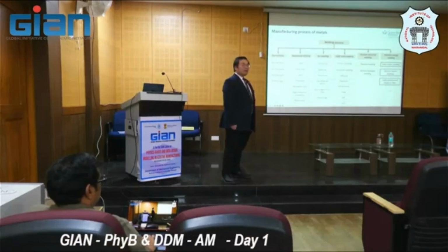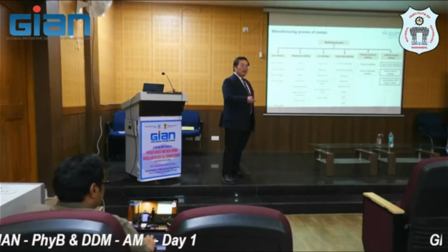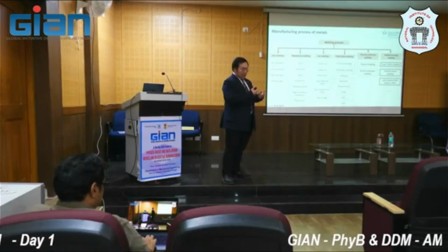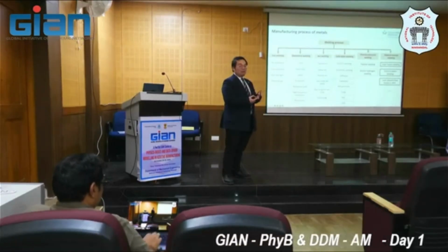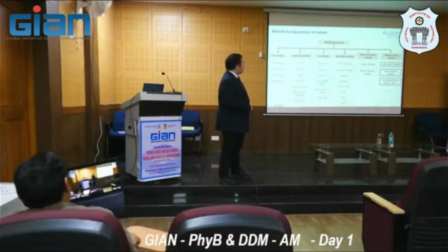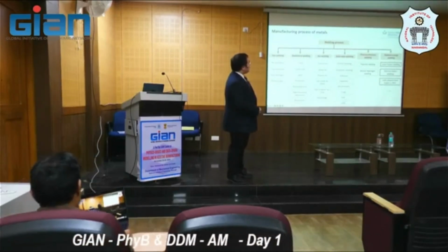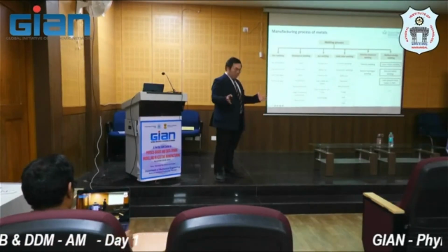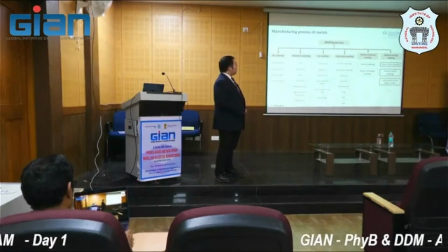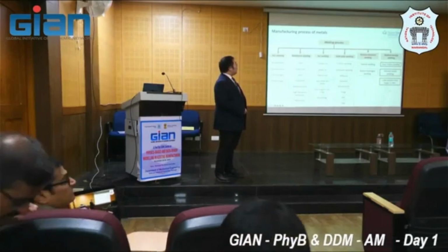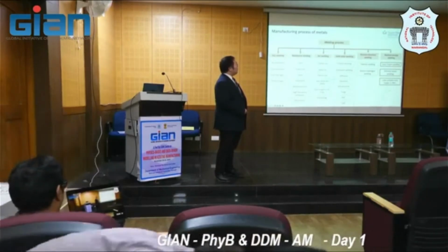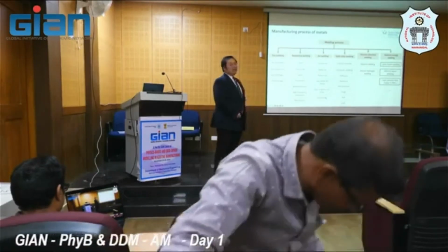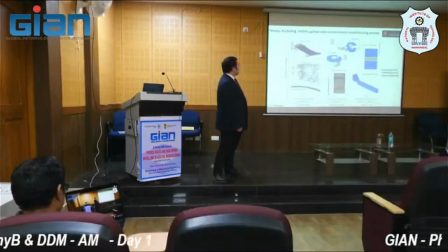But this is another matter of corrosion or embrittlement in nickel, titanium, basically nickel and then steel, which is a big problem. Again, that is another matter for metallurgy. But for today, it's about radiant energy welding, or beam melting-based process. So we're talking about either fusion welding or electron beam or laser welding, and this LPBF is classified in this one for the manufacturing process.